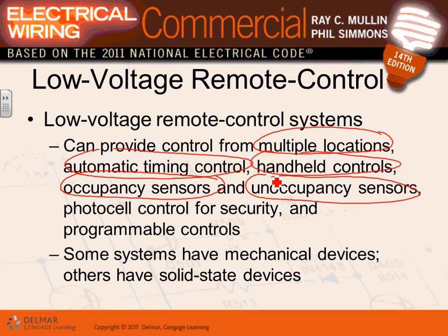Photocell control for security too, you can interface it. And programming control, you can program it to do anything you want. So the whole idea, guys, is to take a fixture and turn that fixture on when we need it and off when we don't. That's what the whole low voltage control system is based on.